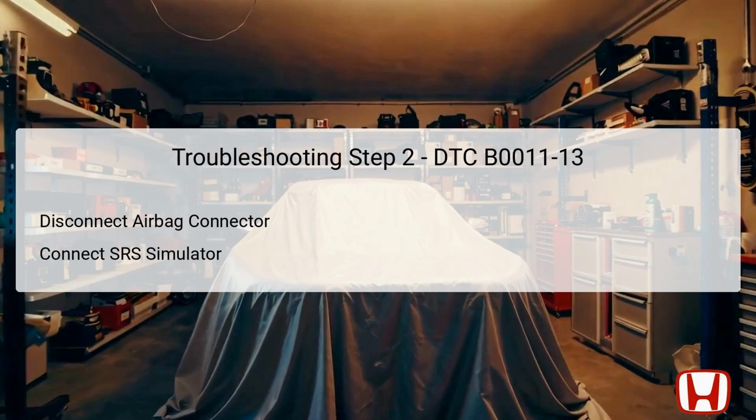The simulator should be securely connected to the airbag inflator connector to allow for proper testing. This process serves to simulate the inflator and helps assess the condition of the entire airbag circuit. It is an essential part of determining whether the airbag is functioning correctly and whether the error code is indicative of a deeper issue within the SRS system.